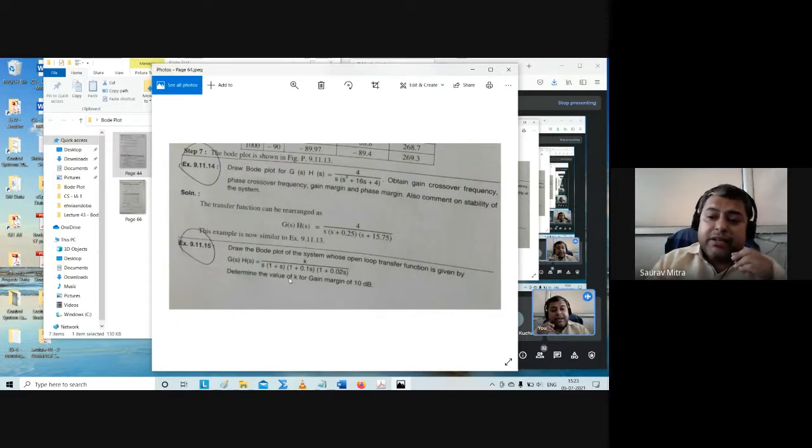This numerical with K will always trouble you in the second order system, in steady state error finding, in root locus, in Bode plot, everywhere this K will come. And what is this K? This K is a gain which you can control externally. This is not a frequency determined gain. In GSHs there is no K here, and in this case I have mentioned K as 4.